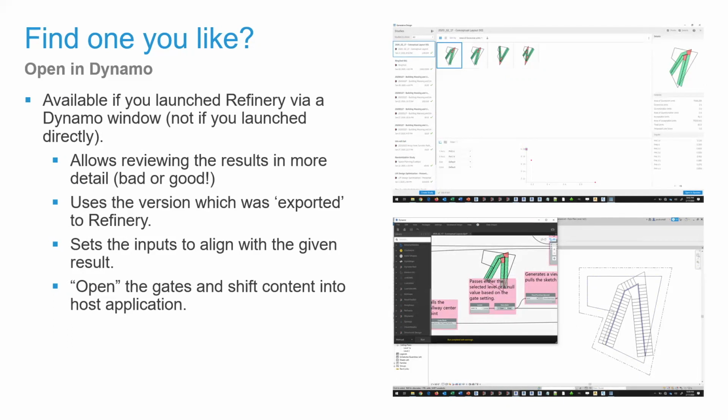So you can see I've actually created rooms. I've highlighted that room there that I picked for the hallway. I don't know why I picked that one. Maybe not the best option. And then all the other rooms as well as room separation lines for our partitions. We could have done other options such as walls and stuff like that. In this case, it didn't seem worthwhile because we're just getting into the overall scope.